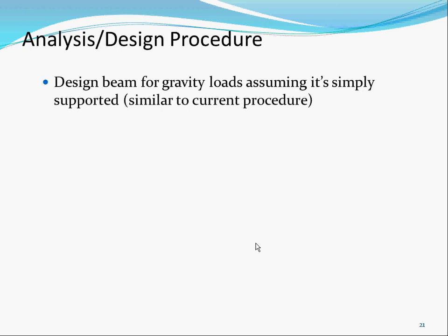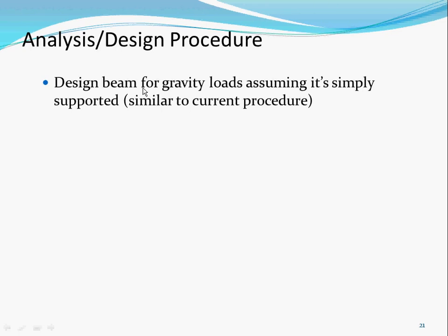Let's say you want to remove the link on the column bottom, you would have to shore it up if the link is actually taking the gravity load. For us, you can take out a link at the column bottom and leave it without having to shore, then just add the link to the column bottom and you're good to go, because you designed your beam for the gravity load as a simple beam for all of it already.